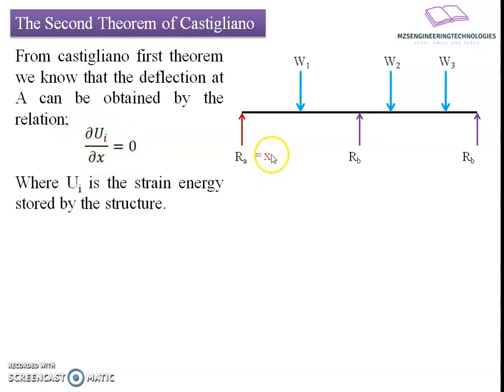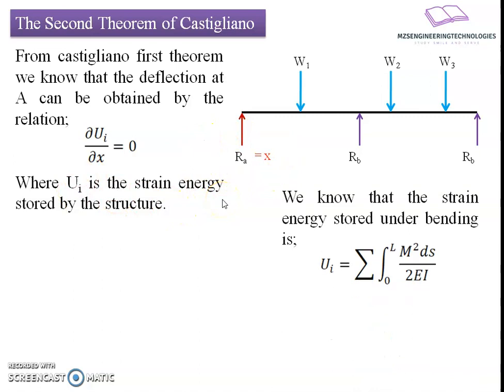Now what we require, what is the maximum value of x? It may vary from 0 to n, but I want a maximum value. So what I will do, I will have the minimization or maximization of this particular deflection which is being caused by the unknown force. Means I am going to minimize the strain energy value with reference to the redundant force. For that, let's take a concept related to a flexural member.